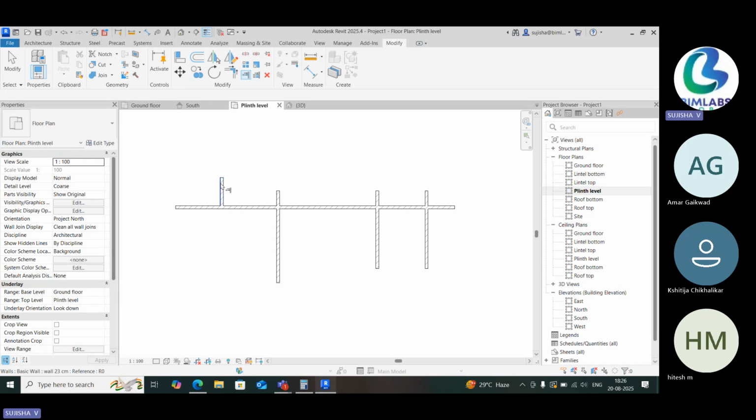So whatever things should be retained, that should be selected, not the cut one. Okay. So what I'm selecting is this trim or extend. This is my base. I need to keep it here. I want to cut this. Okay. So I'll select this. Whatever thing has to be retained, that has to be selected. Okay. Now what it has done is it has trimmed, right? This is actually a single trim option. This is actually multiple trim.